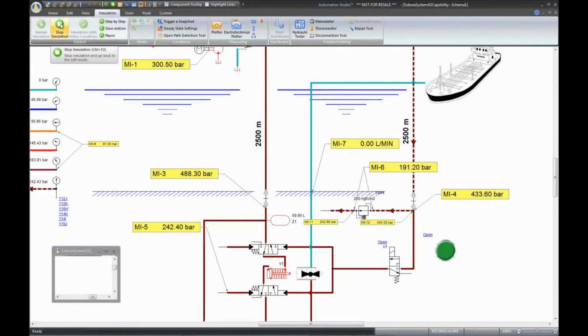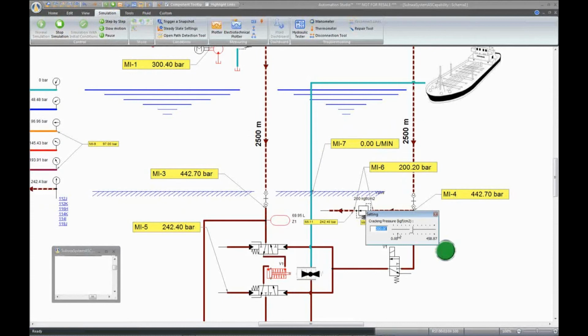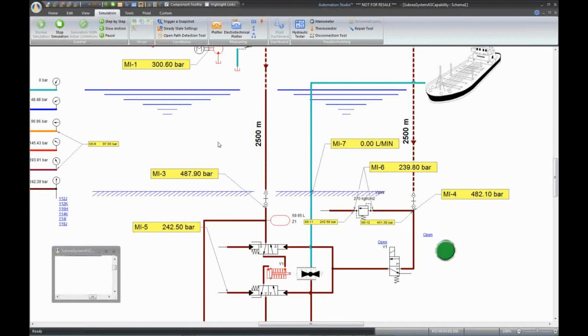You can use a gas accumulator, a mass accumulator, but you can also use a cylinder, and with a cylinder you can adjust the effort and make it variable, which can be very useful. Depending on your need, you can use many components to build this pressure compensated reservoir.